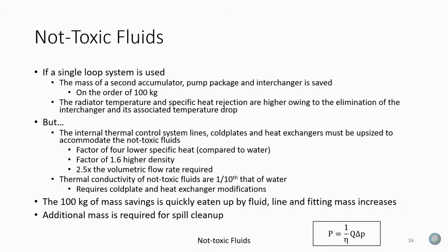Now, you might ask, we've had visiting vehicles that go to space station that are okay with these kind of fluids. And the reason is that these are systems that you can test on the ground and show the leakage, and nobody is touching anything in this system while it's on flight. And so that's how we get around that: the allowable leakage can be taken up by the trace contaminant control system on the space station. And so that's how we're able to use those fluids on vehicles to visit space station.